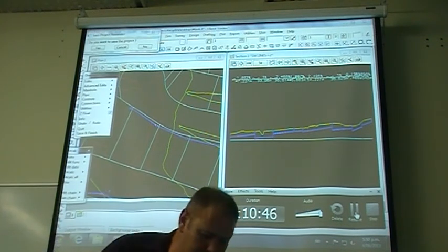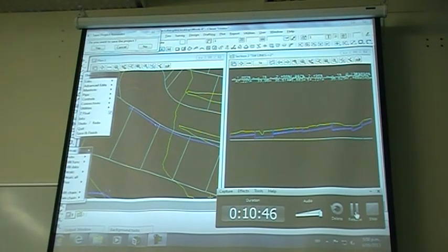Obviously, if this is a rough lot layout, a boundary scheme, and this is the highest point and this is the lowest point of it, and I put a manhole in here that's 1.8 deep, and I've got 4 metres of fall across the site, then by the time they build this house and the drainage comes out at the lowest point there, it's going to end up a couple of metres below the manhole that we're trying to get into.